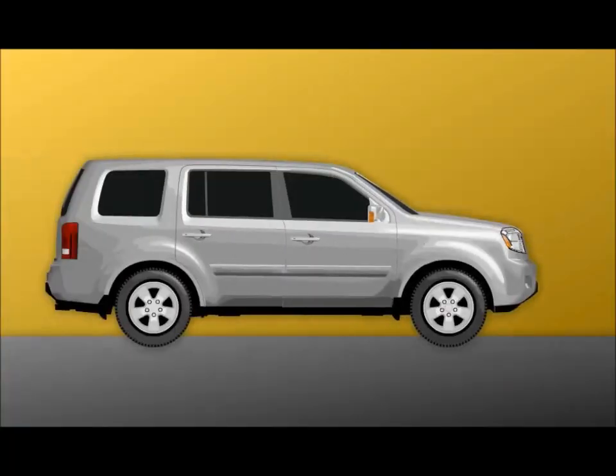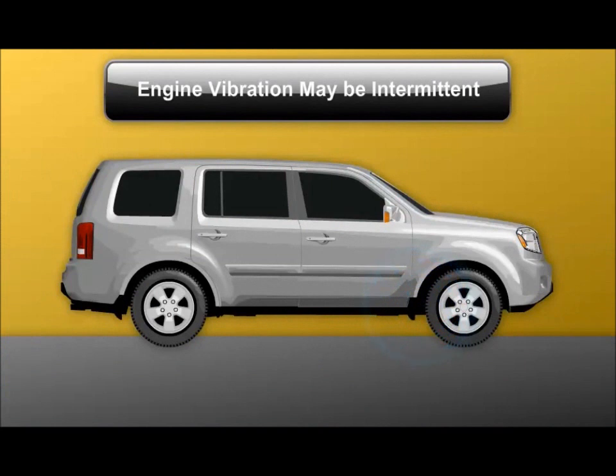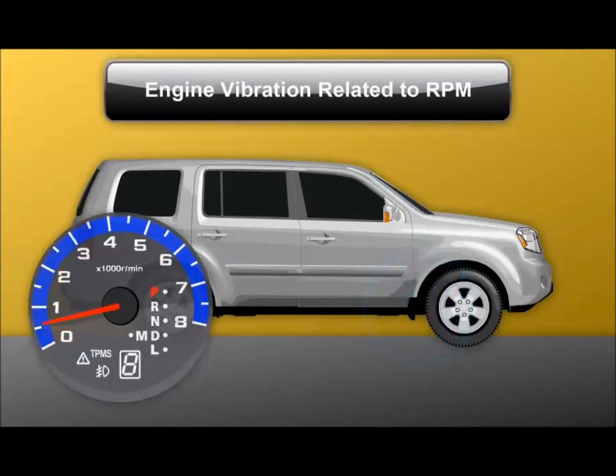Like vibration transfer, engine balance problems may only appear at certain times. The vibration will relate directly to engine RPM rather than vehicle speed or load. If the vibration always occurs at a specific RPM, you've probably identified an internal balance problem.